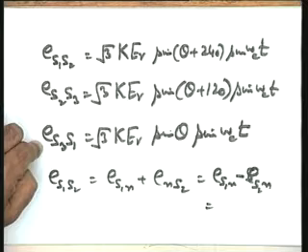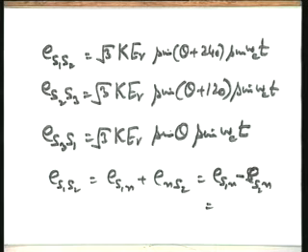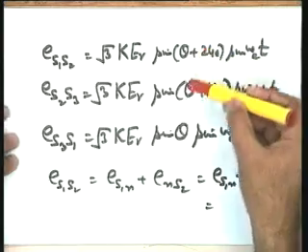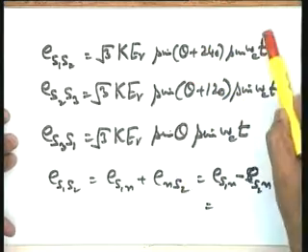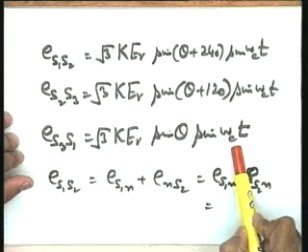With respect to time, is the device three-phase or single-phase? You have very rightly answered it. Since the voltages are in phase in time, it is a single-phase device, surely, because only the amplitudes are changing. All the three voltages are in phase.